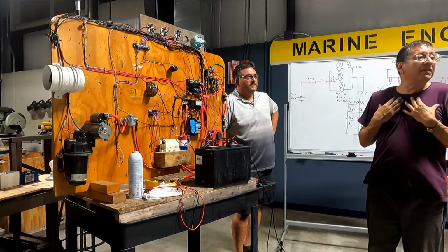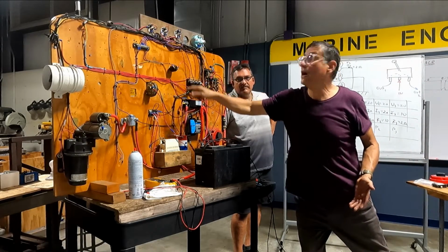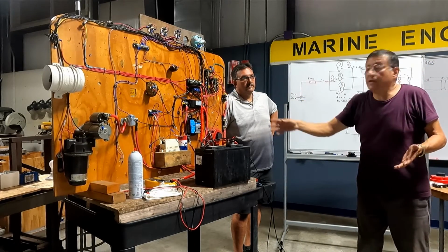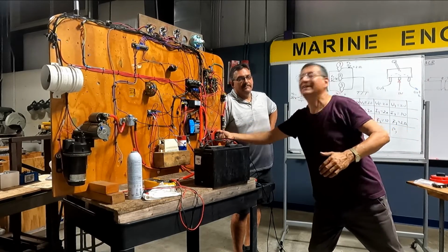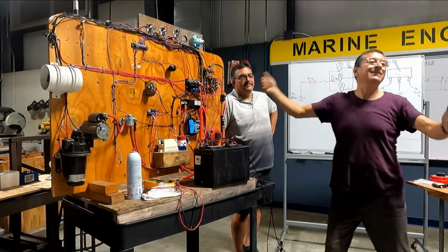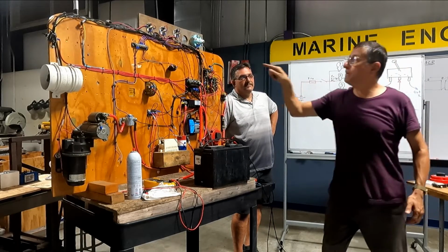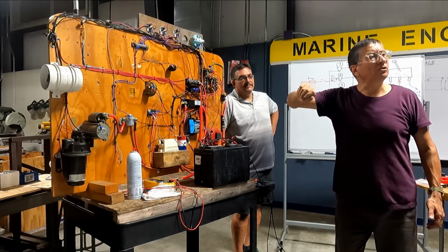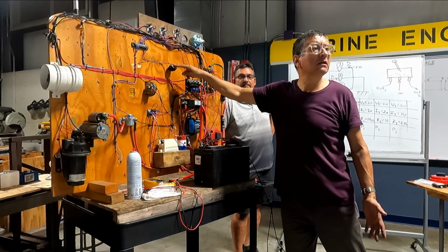Now, if I have power in the battery and the battery is good, it's supposed that I have power here. What happens if I don't have power here? You have a problem in the wire, probably on the switch selector. Right now this is the position. Let me check. Yes, right now I have power here. Okay, you have power in position B. Let me check the second position. I don't have power here.